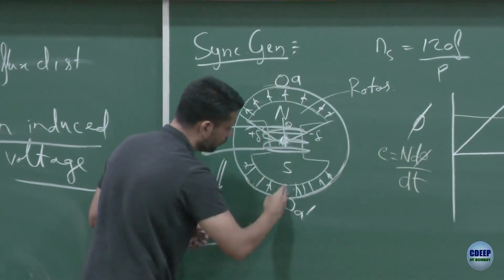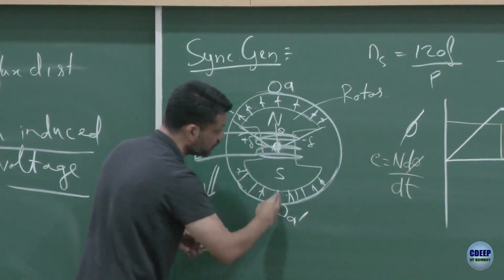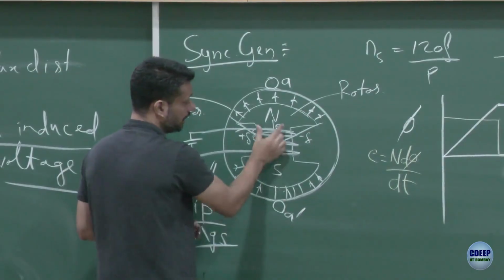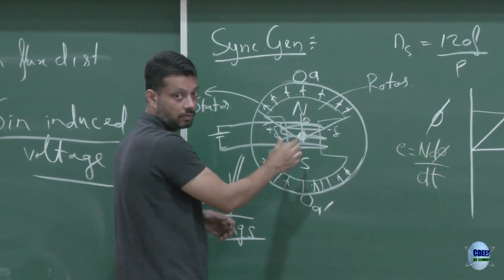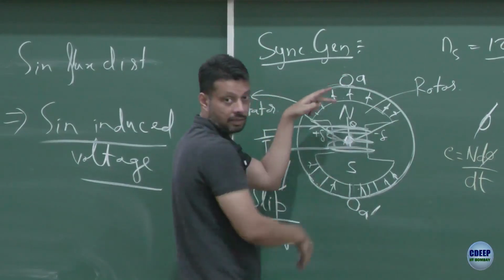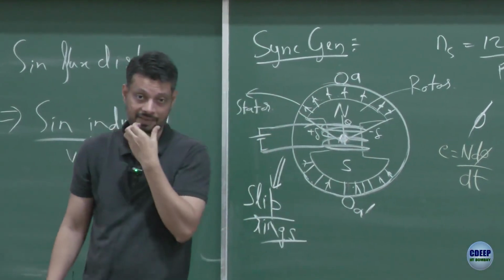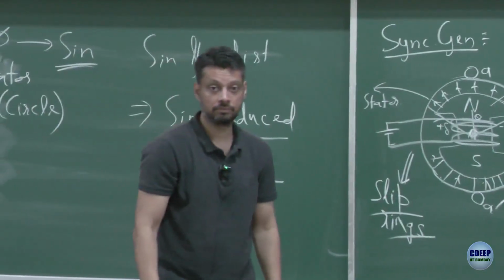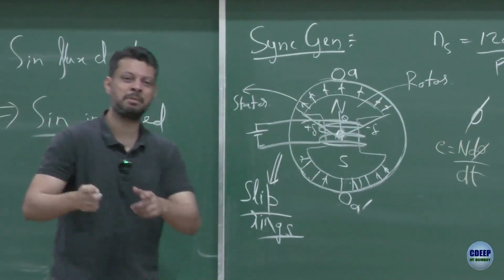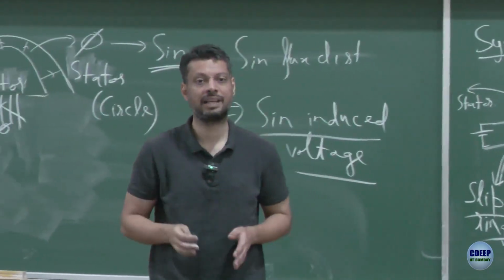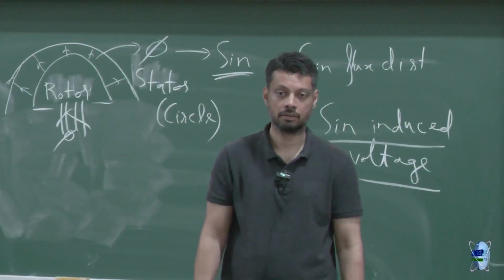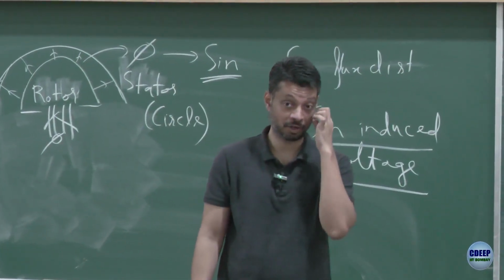This is the coil. So how much net flux is crossing depends on what flows through this part, right. So if you take these 2 points, it's the flux crossing this which matters. Lines would most likely be normal because that's a minimum reluctance path. Lines would most likely try to take the shortest path. You don't have to take the cosine component.